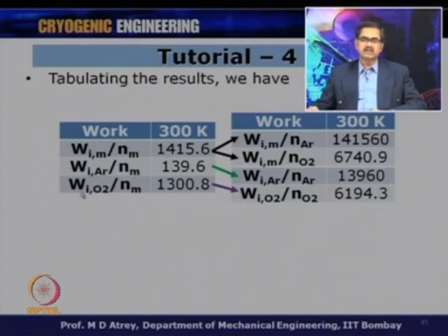It basically one can understand from work of liquefaction per mass of gas which is compressed. If you remember my earlier topic, work of liquefaction per mole of gas which is liquefied. Similarly, here work of separation per mole of mixture or per mole of oxygen or argon or nitrogen or whatever. So, understand the problem statement and represent your work of separation per mole of mixture in terms of per mole of oxygen or argon or nitrogen for that matter.